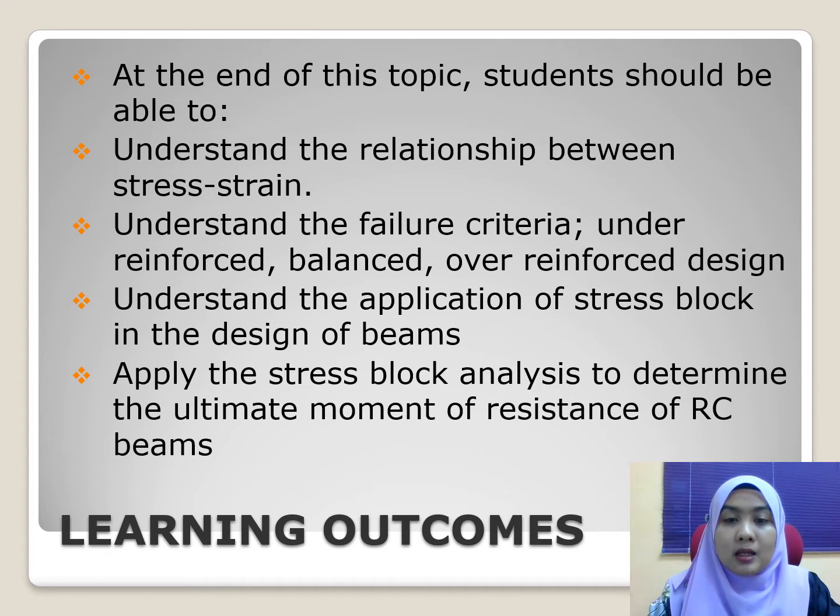You need to understand the application of the stress block in the design of beams, and then apply stress block analysis to determine the ultimate moment of resistance in a reinforced concrete beam. So basically, we are going to look into how we get the formula in design.